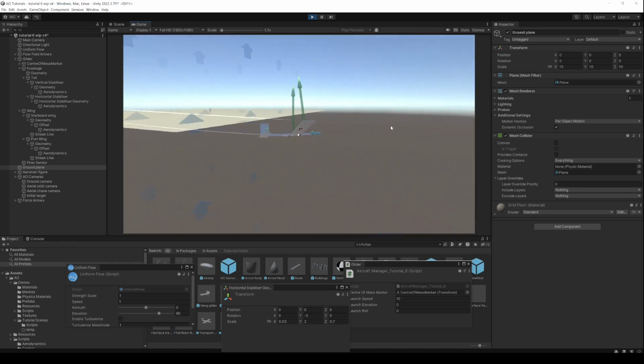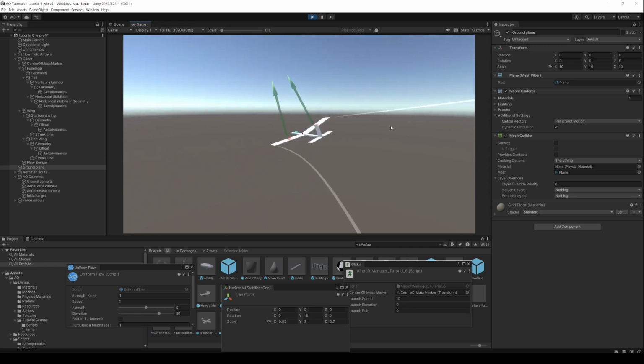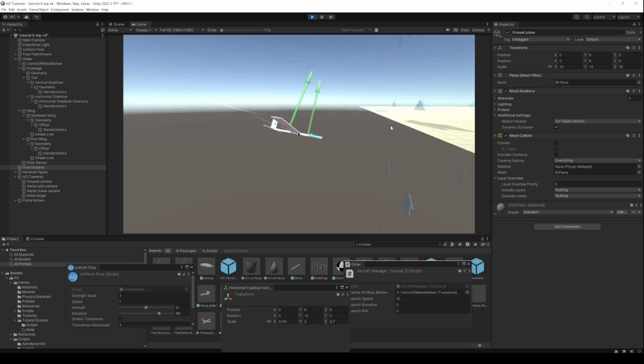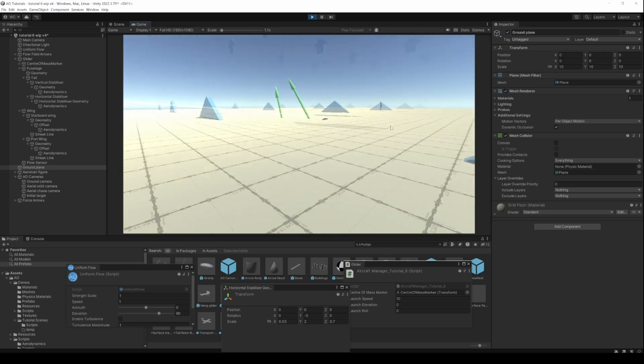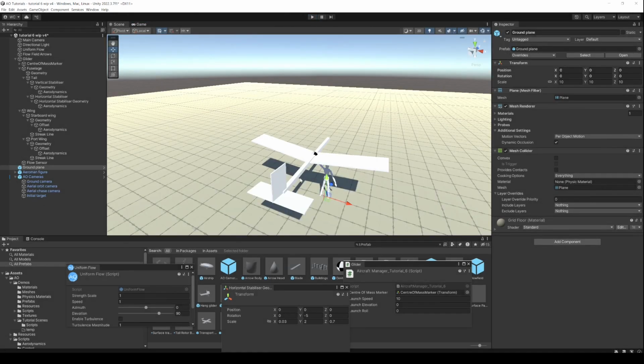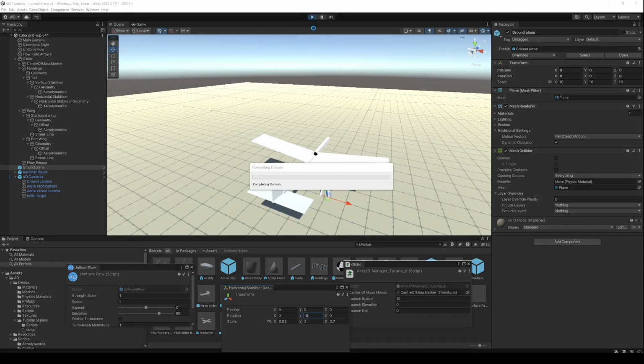There we have it, we're flying. Didn't quite make it back to level ground, so that's fine. Let's try adjusting the trim a little bit. If we now change it by another 3 degrees to -8, that's going to be flying a little bit slower, a little bit more lift, and let's see if that's enough to keep us above ground.